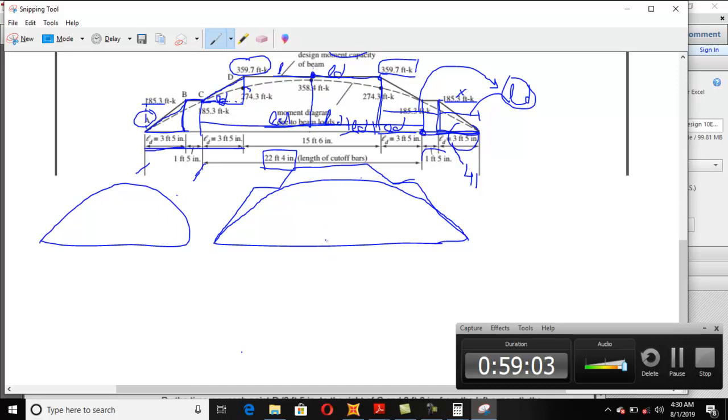And then you will need to calculate those points, like this point, clear, like this point, clear, like this point, and like this point. As you know the moment capacity at this point, because at this point you have two bars and the two bars capacity is 185. Clear? So 185, and as it remains constant, this distance must be equal to LD.